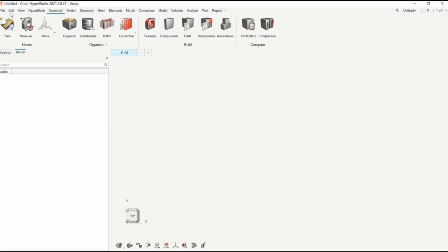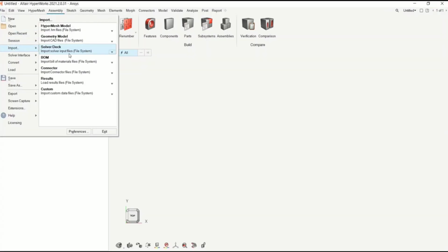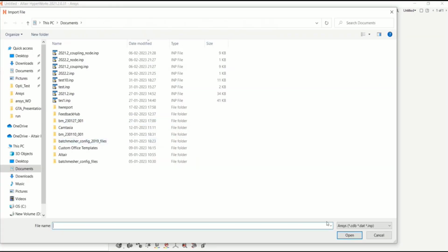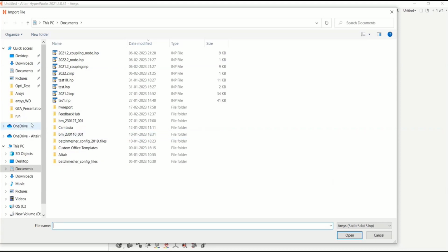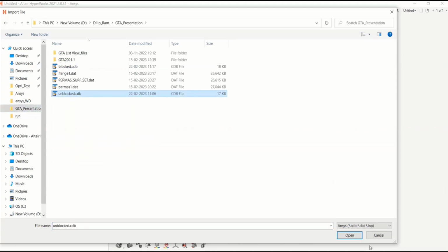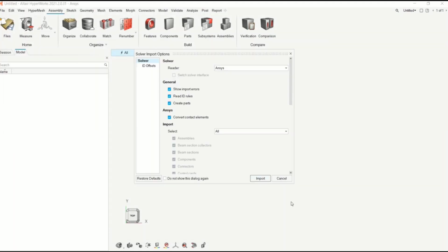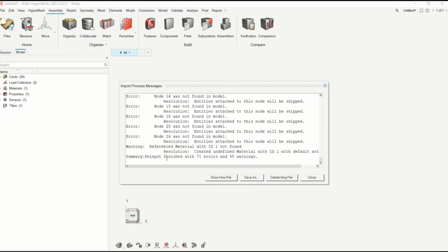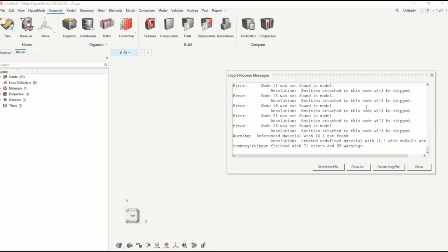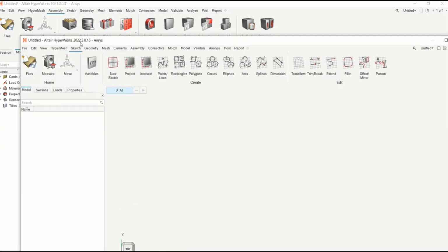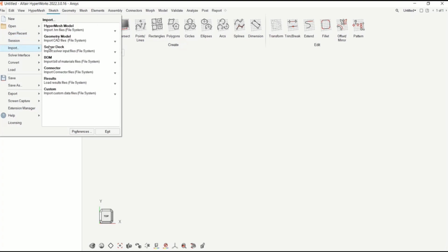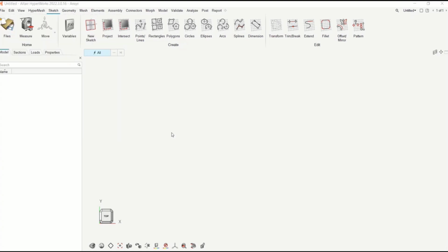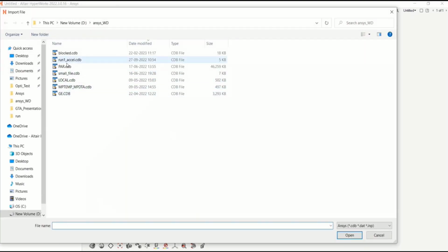So if I had imported this in the earlier release, with no support of those blocked and unblocked formats, I would not have got any model, but would get a series of warnings, because we never supported unblocked format for the node. Now, with the latest enhancement in 2022.2, if I import this model, I get the nodes, I get the CP, I get the temperature, pressure, and everything.